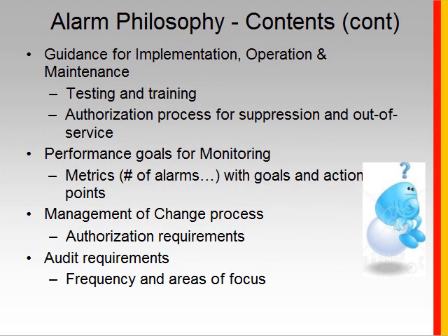The philosophy will also contain information on how you will test and train and the frequency for when you'll do that, what process you'll use for management of change, who's allowed to make changes, what authorization and review process is necessary to make changes to the alarm configuration, and also a definition of the performance metrics.